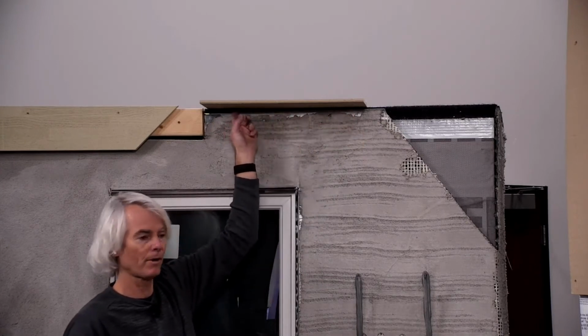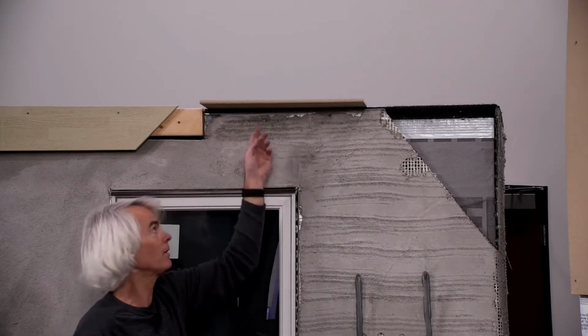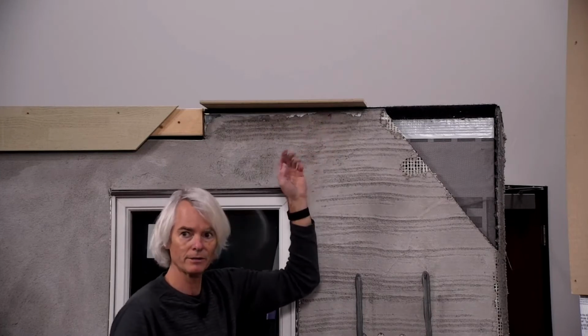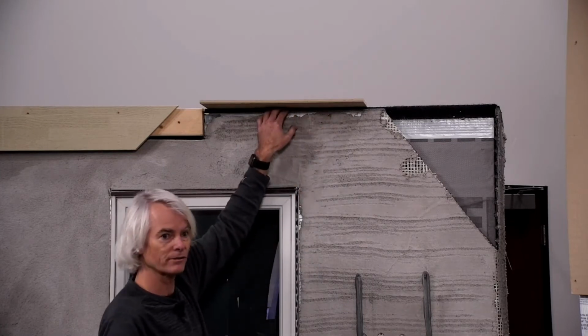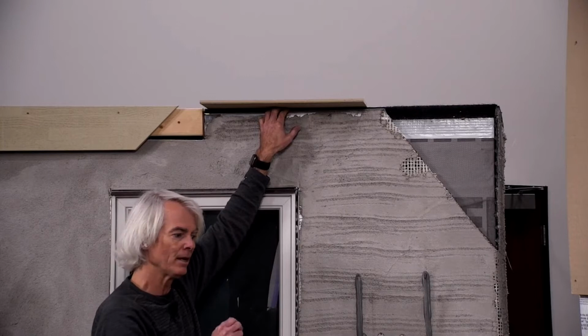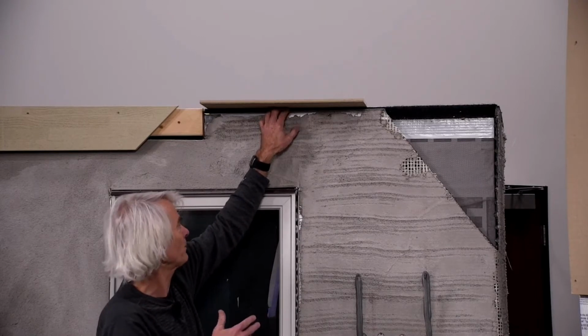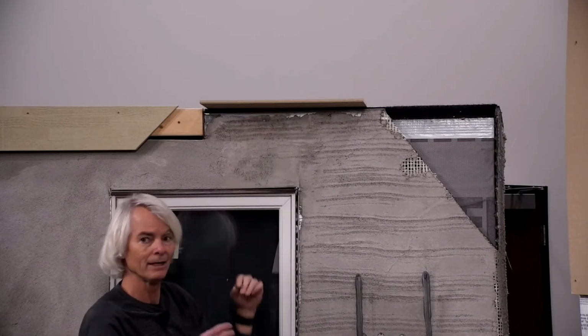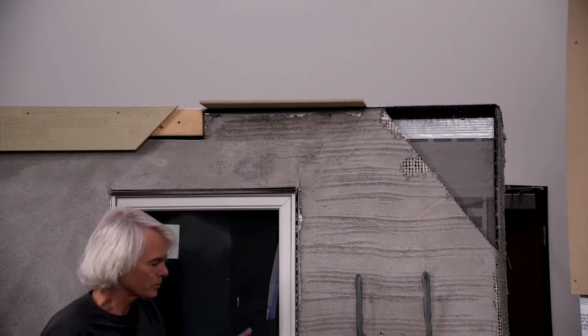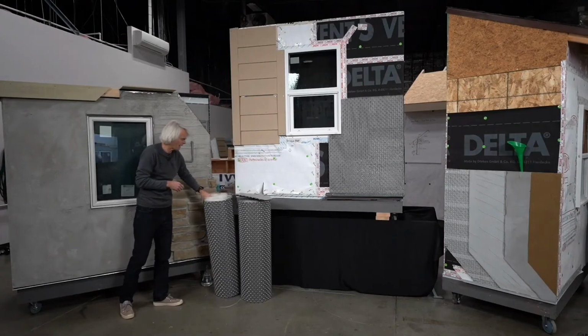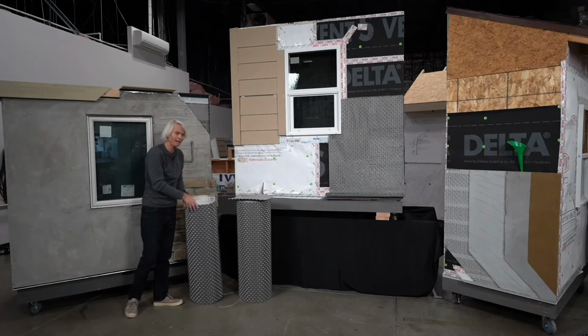So from the ground, 20 feet up, you're not going to notice that. It's a nice visual sight line that's put on the building, but that's facilitating for this ventilation air to escape, and hopefully it's carrying water or other things with it to help dry that wall, so it's going to accelerate that speed.